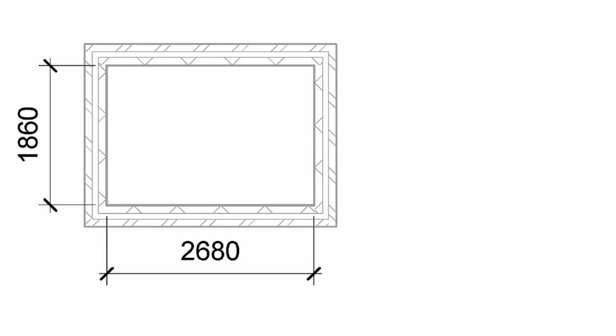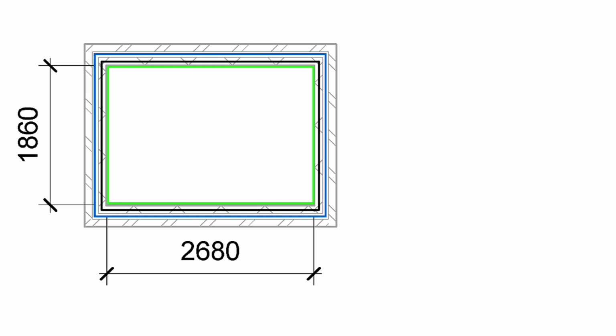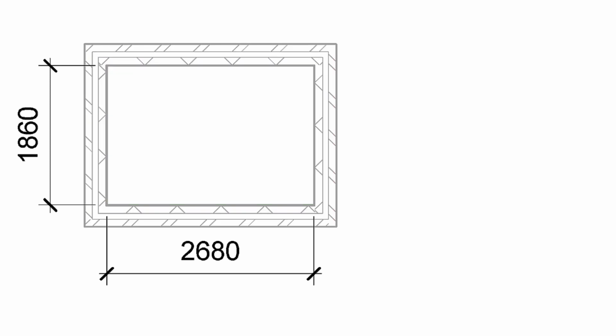So, how do all these centre line lengths differ from each other? The differences in lengths are the different distances around each corner. Let's expand the inner girth to the centre line of the inner blockwork skin, cavity and brickwork outer skin. If there were no corners, the girths of these centre lines would all be the same. The difference in girths then is the extra distance around the corners, as can be seen in the animation.